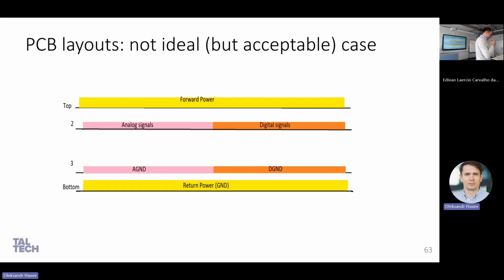Because when you do vias between layers, this is how your PCB production cost is calculated. First, you remove copper, then you make drills, and then you put together the first two layers, then the third, fourth. But if you have blind vias, the technology is possible, but it's much costlier.